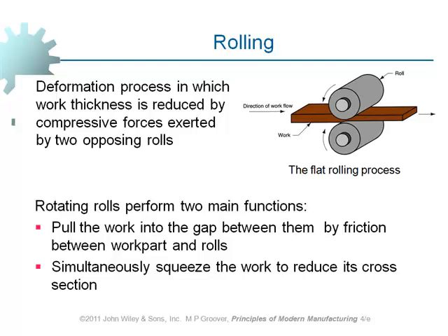So as we're subjecting the material to more and more cold working, a larger number of dislocations are trapped and cannot move any further. As a consequence, material is stronger. You cannot deform it as easy as before because now there are fewer dislocations available which can make the move. And we can continue this until material fails because material cannot be subjected to any further change of shape at a given time. So if it is still subjected to further deformation, material fails.